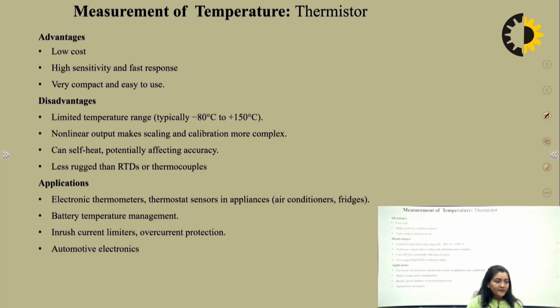Non-linear output makes scaling and calibration more complex. The characteristic is non-linear, so obviously, when you are dealing with non-linear systems, there are some constraints. It can self-heat, potentially affecting accuracy, and is less rugged than an RTD or thermocouple.